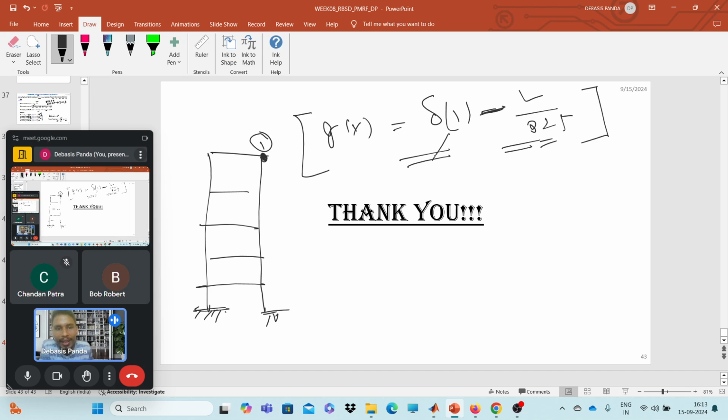Here, the random variable del, you can directly call it from the model, whatever you have made in STAAD or SAP or ETABS. You can directly get it from there, and you can perform the rest of the analysis and check what will be the probability of failure. This is the one case.